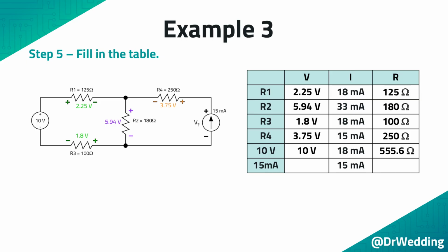Ohm's law will get a lot of the values on the chart, but one value, the current supply, does not have enough information to fill in the missing values. But KVL will come to the rescue again. If you start at the star and go clockwise around the highlighted path, the voltages will add to zero. The only way this can be true is if the voltage across the current supply is 9.7 volts.